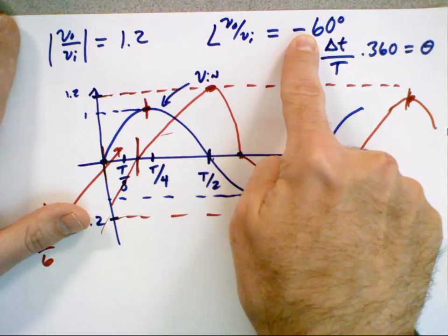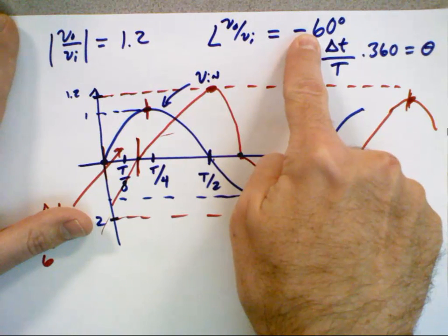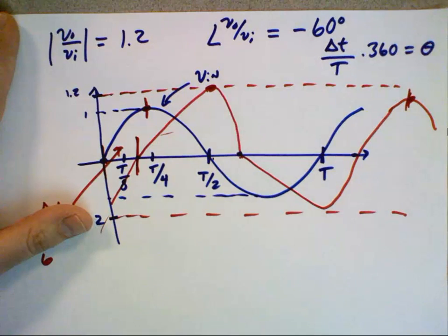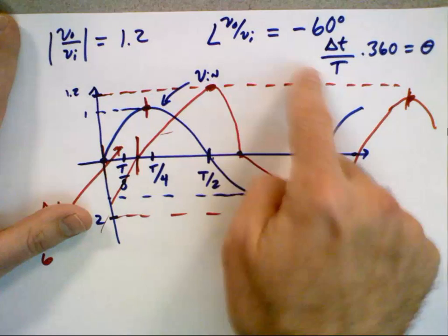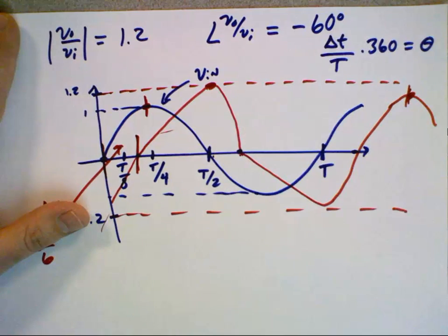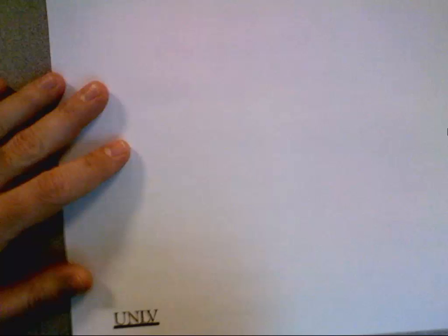I mean, it's really confusing, right? That's why I like output before, output after. And if it's positive, you flip it. And then the delay is just the percentage of the period. That's the way I remember it. I never remember the equation. I always remember, oh yeah, delay is just the percentage of the period. Okay? All right. Let's move on to an RC circuit.